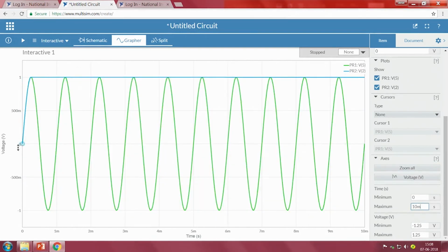If we observe, the output initially keeps on increasing, meaning the capacitor starts charging, and it is charged to a value of 1. Why only to 1? Because the peak voltage that we applied is only 1 volt, and since we do not have any discharging path, the capacitor stays at this particular point, the maximum voltage.